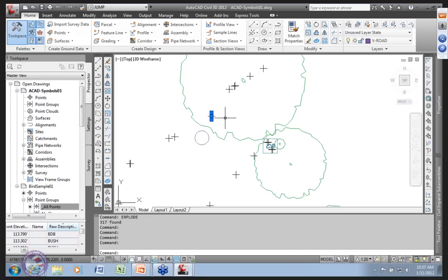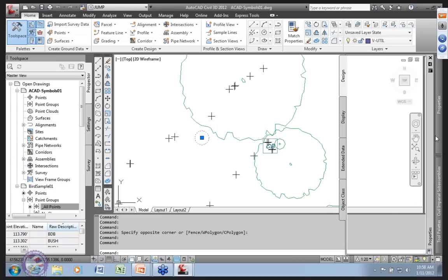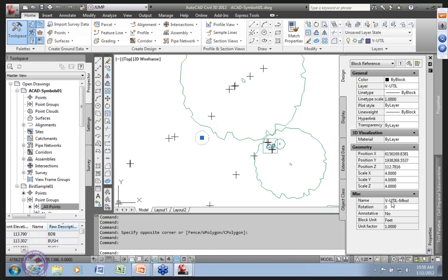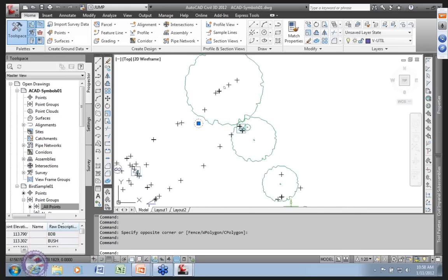Since they are pointing to a style, I wanted to point out, they just become little lines, no symbols. So be careful of what you employ. The symbol, in fact, right, becomes the named block, referred to in the style after the explode process happens. Okay, so this will be actually a real block if you do that. Okay, so if you want these little crosses to stay coherent, they got to reference a named block.